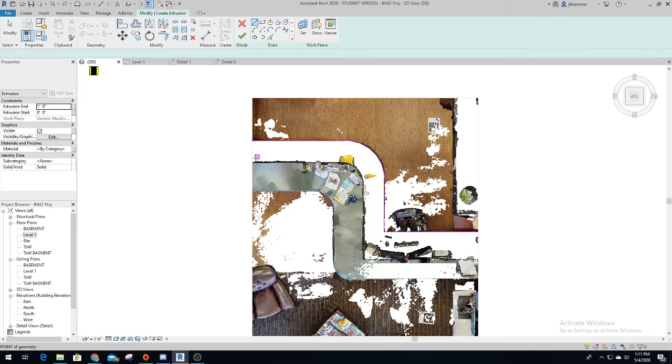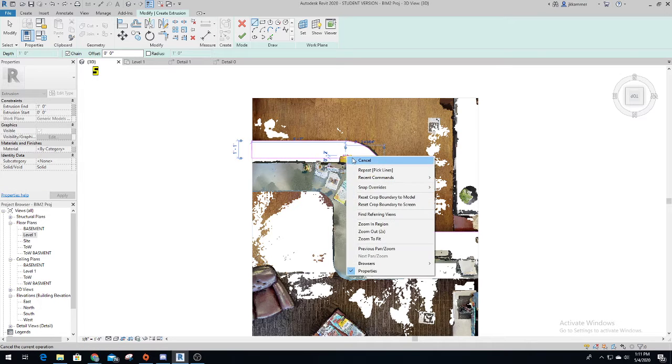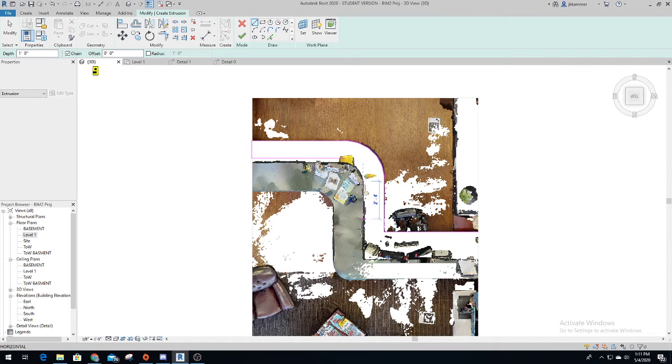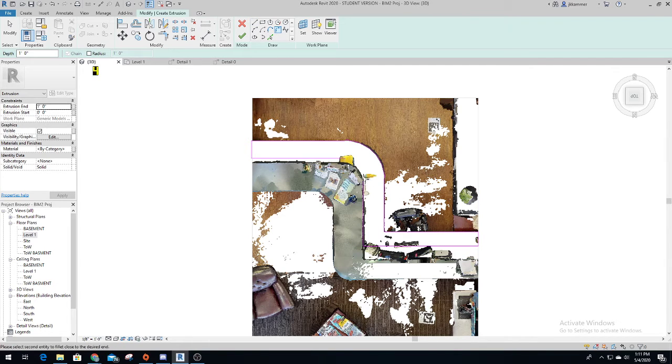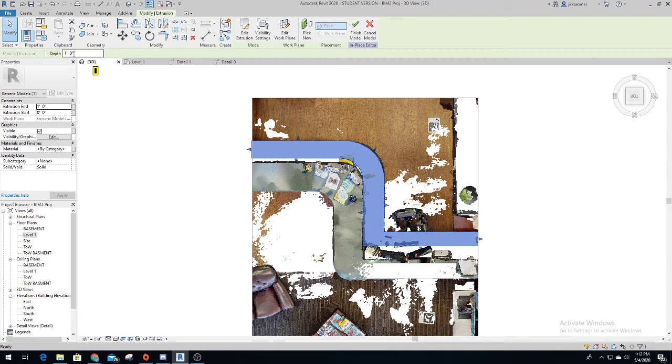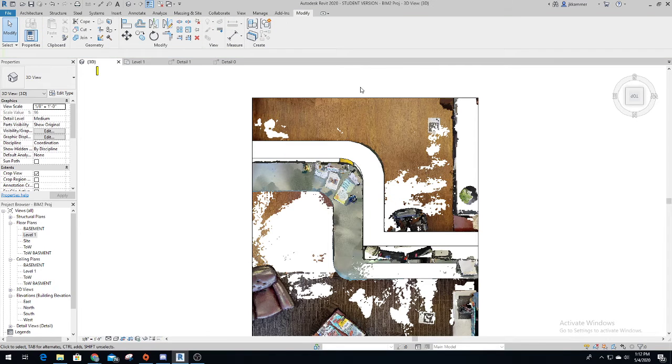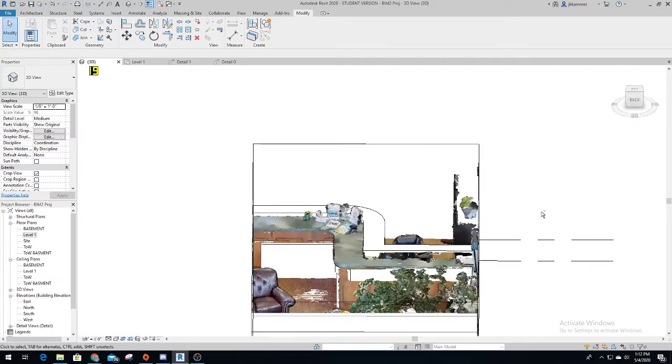Sure. I'll connect that point in a second. And then we could use this to connect these two lines together like that. And there. So finish the extrusion like last time. We want 1.5 inches. Finish model, and there you have.